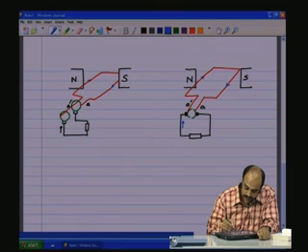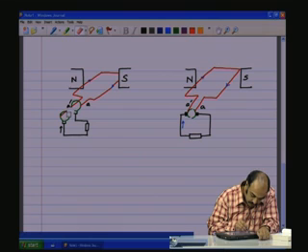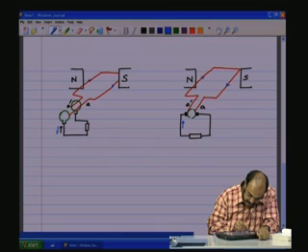Through the brushes. Whereas here, the current, sorry, once this has made a rotation, this would have gone to this point, that is the connection here, because A is connected to that slip ring, and A dash is connected to this slip ring. Okay. So, now on the position getting interchanged, now A is at the south pole, like here. The direction of current in the brushes has reversed.